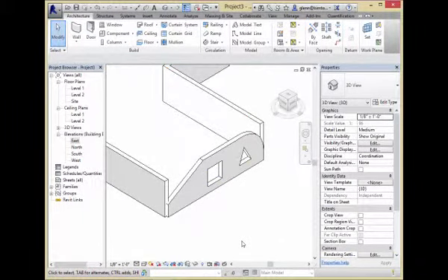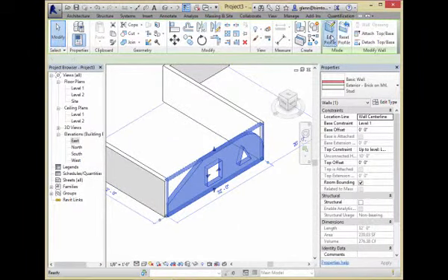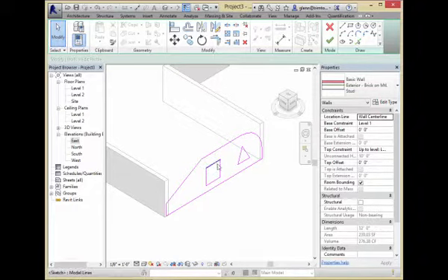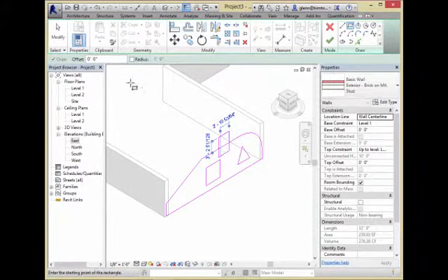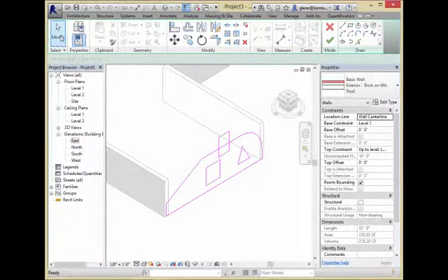So it tends to be pretty easy, but let me tell you about the part that doesn't work. Okay, we have to watch out for when we're doing this technique, and that is as follows. As you go through and edit the profile, so far so good, not too awfully bad. What it doesn't like is anything overlapping or hanging out. It really likes these closed loops. So, for example, if you do this, okay, that's unhappy. It's not going to like that because it's got some sort of intersection.